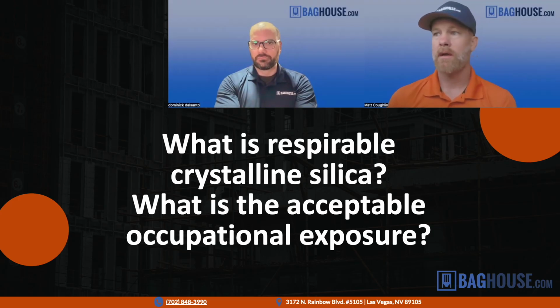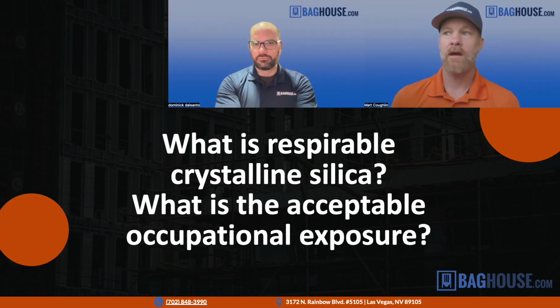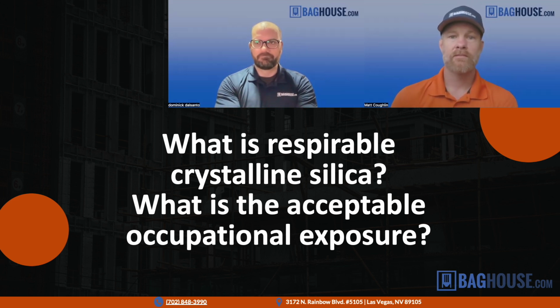So I won't comment on the specific limits again, because they tend to change, but you need to check if you have silica dust at your facility. You're almost certainly regulated by the OSHA and MSHA exposure limits for respirable silica. So you've got to check the regulations and make sure you're compliant. If you're not sure, you need to go do some testing with the sniffer and make sure you know what's going on in your facility, and design a dust collection system so you can get that out of the facility.